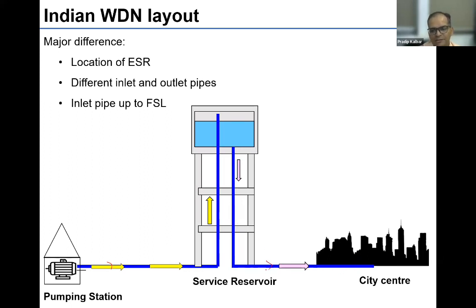So the entire demand is basically supplied through reservoirs, and we typically have 1/3 of this particular demand volume stored in this particular reservoir. Now what happens is, these cities do not have any control on the withdrawal. They have storages, there is no metering, people do not close the tap. So a tremendous amount of withdrawal happens through this particular system. And we are working with 7-meter pressure, which is not yet achieved. So a very long distance we have to go if we have to raise to a higher pressure.